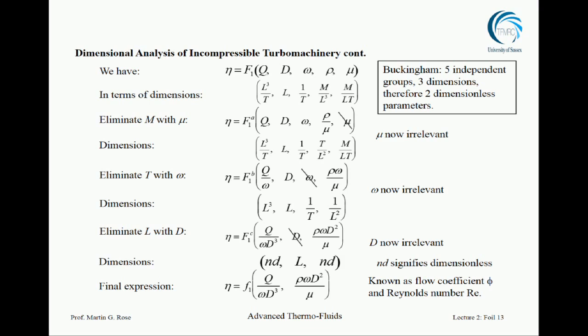You may remember, hopefully some of you do, what Reynolds number should look like. And you might be thinking, that's wrong. It shouldn't look like that. It should be rho v d over mu. What we've got here is rho omega d squared over mu. Anyone got any ideas why? Why is that a Reynolds number? A corrected Reynolds number, something like that. We add something to, multiply it by. No, in fact, it's a perfectly genuine Reynolds number.